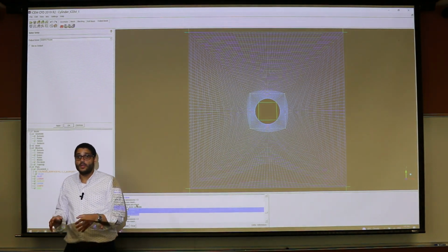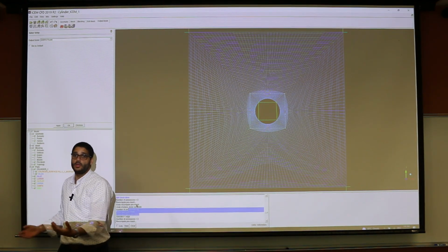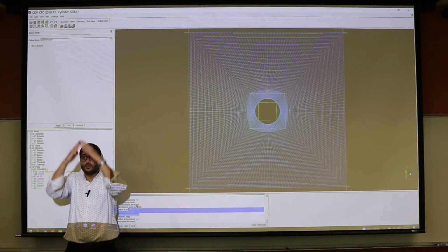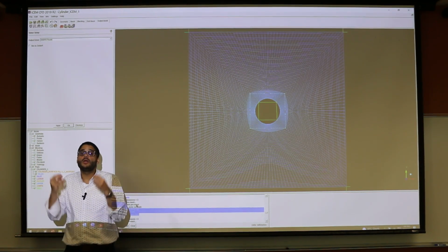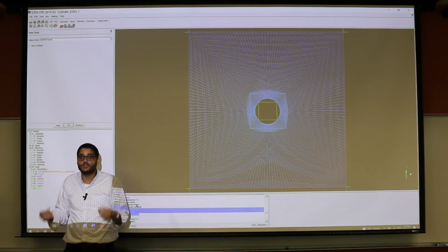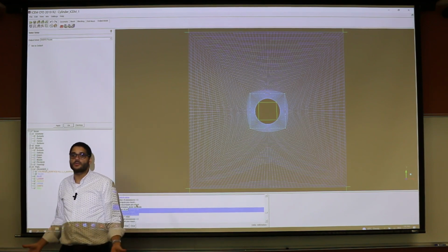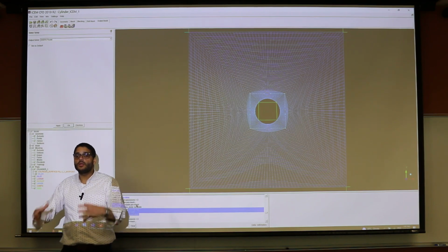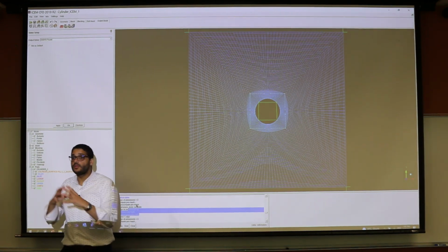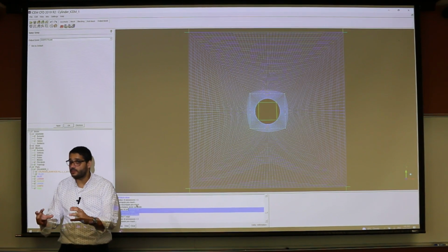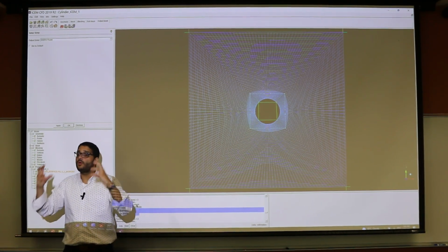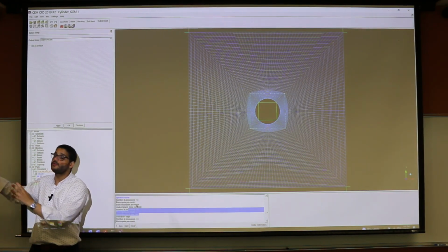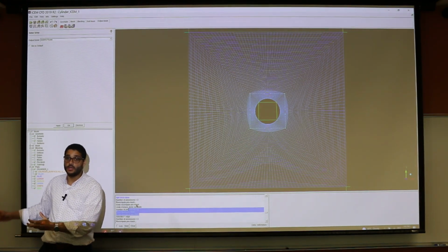Why is that? It's something related to computing. Displaying information in a window on the screen is the slowest process that computers can ever do. So that's why I totally encourage dealing with Fluent in the text user interface. It will be much faster and it will help you a lot in doing a CFD simulation on HPC.